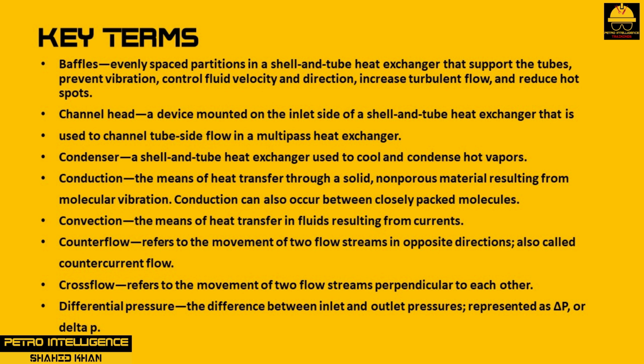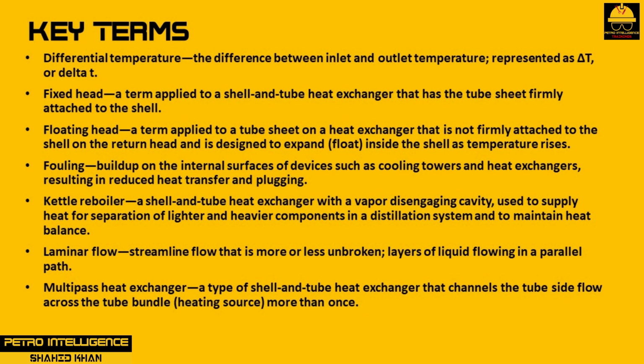Crossflow refers to the movement of two flow streams perpendicular to each other. Differential pressure is the difference between inlet and outlet pressures, represented as delta P. Differential temperature is the difference between inlet and outlet temperature, represented as delta T. Fixed head is a term applied to a shell and tube heat exchanger that has the tube sheet firmly attached